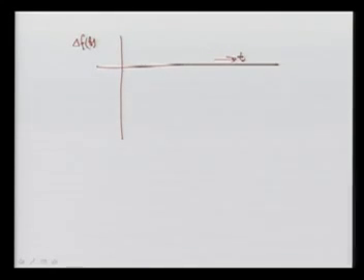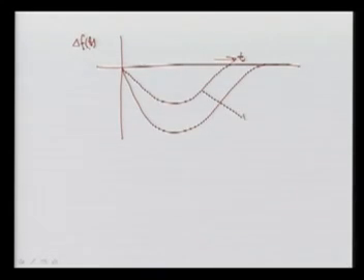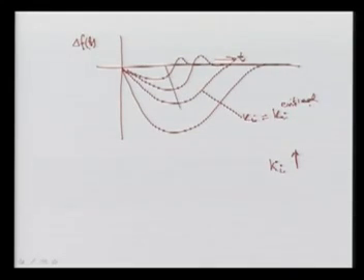So what are we going to get here? Let's suppose this value is somewhere critical, let's suppose this is your Ki equal to your Ki critical value. Now as I said, the Ki is increasing, it shows that we are going to get the oscillatory response. So if this is the Ki critical, and from that you are still increasing, what will happen? You will get your oscillatory response, and finally here like this. So this is the change in Ki, as you are increasing.